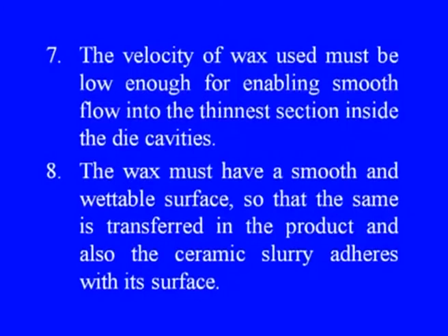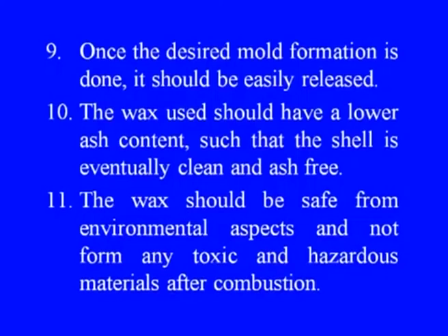Number 8, the wax must have a smooth and wettable surface so that the same is transferred in the product, and also the ceramic slurry adheres with its surface. Another important point. So, better the smoothness of the surface of the pattern, better will be the surface of the part or the cast being produced, and generally wax will offer a better surface finish as far as the patterns are concerned. Number 9, once the desired mold information is done, it should be easily released.